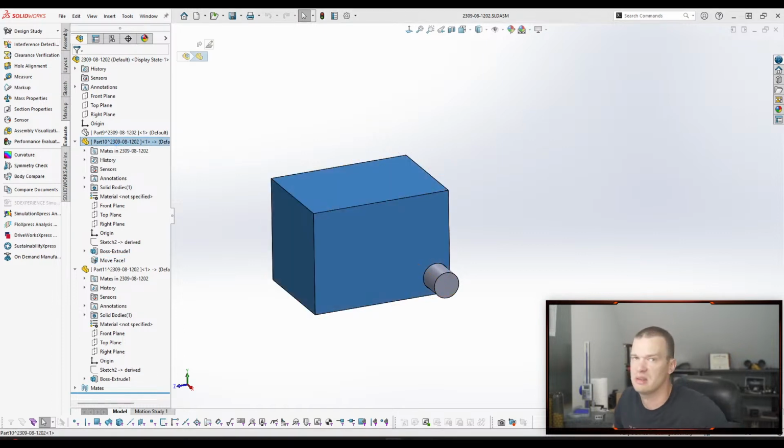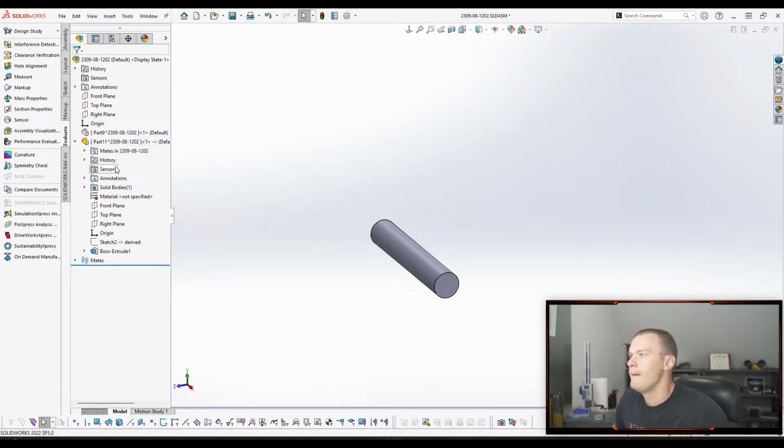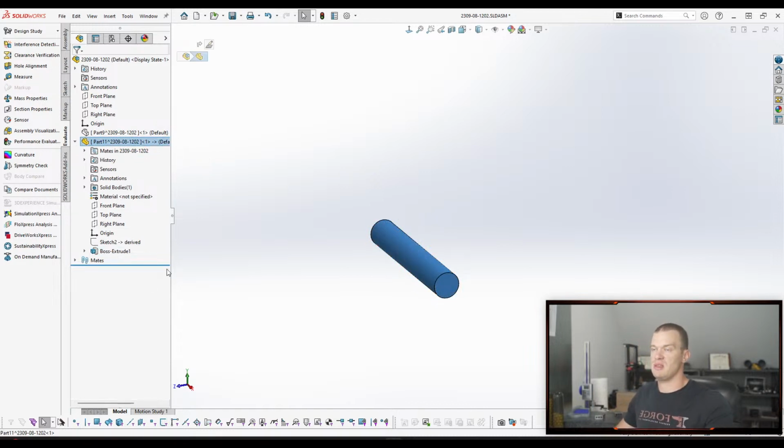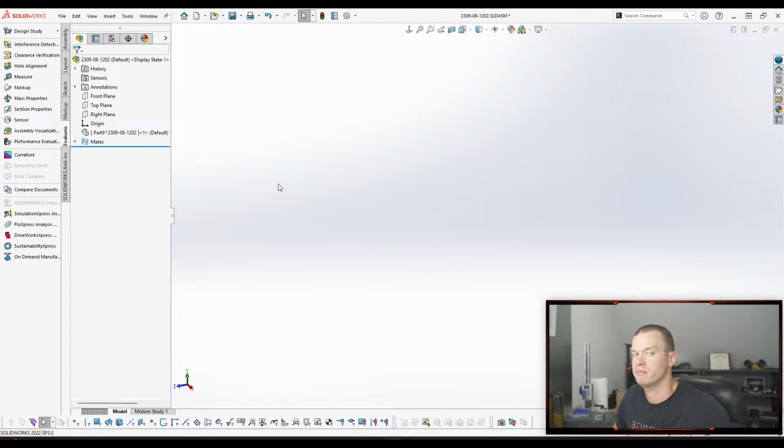So we'll probably delete these. And you can see that that's one of the strengths of skeleton sketching or top-down modeling, good modeling practices right there, right? We just deleted an entire part out of this assembly, and our feature down here didn't break, because it wasn't referencing any geometry in that part. So we can take them out, put them back, and not have our trees explode and get all angry.